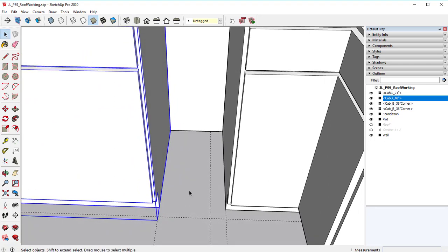This next one, so we have a 11 3/4 inch space. The cabinets that's going to go here are every 3 inches, so we're only going to be able to fit a 9-inch cabinet here. So what we're going to do is we'll create a 9-inch cabinet and then have a filler space in here into this corner to separate out the 2.